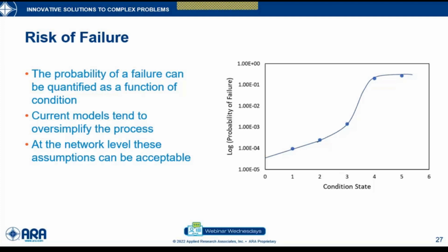So when it comes to geotechnical assets, people have looked at risk, but in terms of failure, of total failure. So risk was defined, for example, in terms of cost. What is the expected cost given the probability for a given asset that will fail in 5 years. And as you can see to the right, this probability of failure is related to condition state. And this is how you assess the risk. So if you have an asset, for example, at condition state 2, let's say, then you have a probability associated with that asset that it will fail with that much probability.